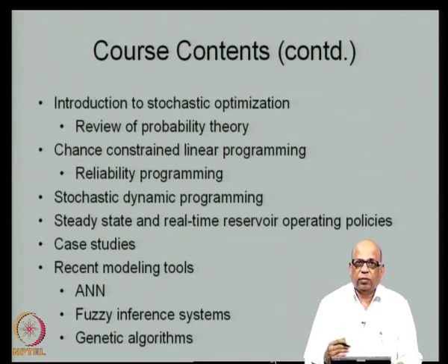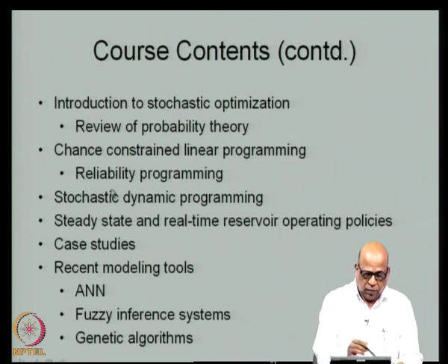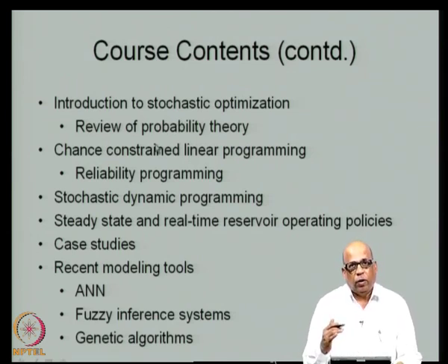of the reservoir systems. Let us say in a monthly time period, 10 daily time period for irrigation systems, for hydropower systems daily time periods, then for flood control systems hourly time periods, and so on. So, we will be able to synthesize and integrate whatever we have obtained through the stochastic optimization as well as the deterministic optimization for day to day operation of the water resource systems.